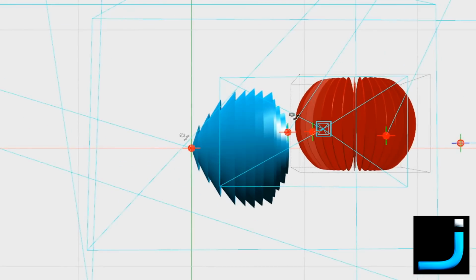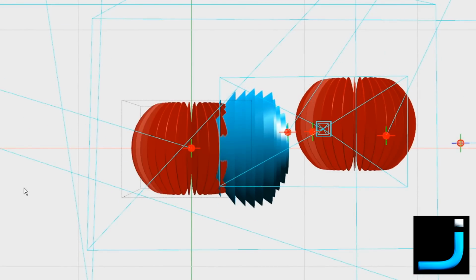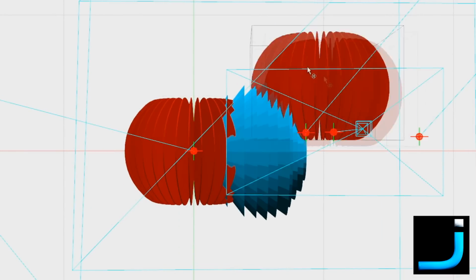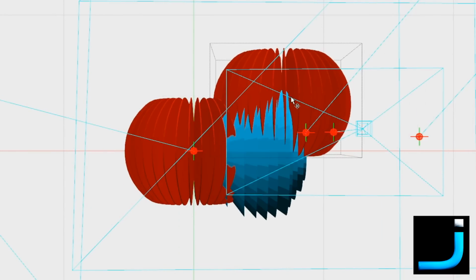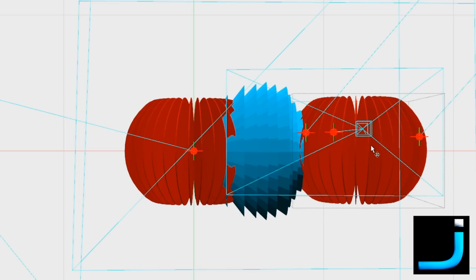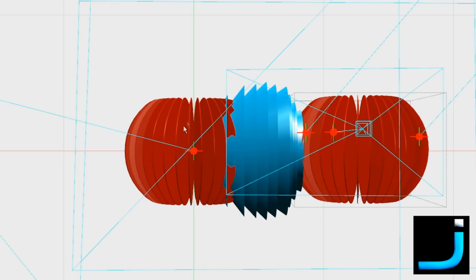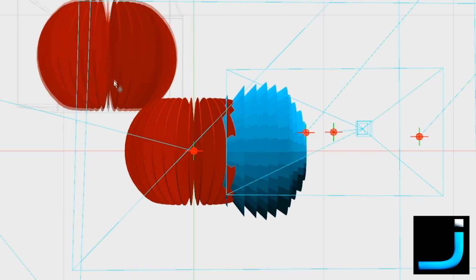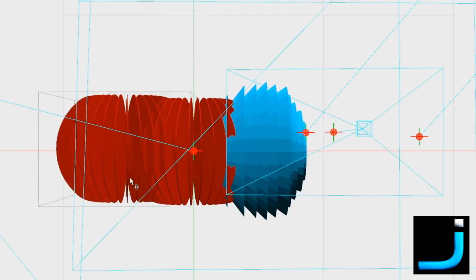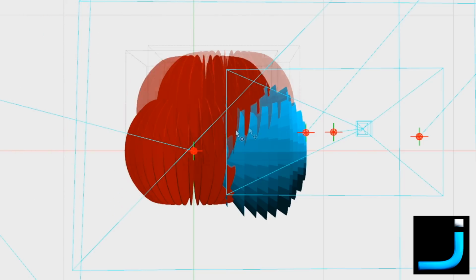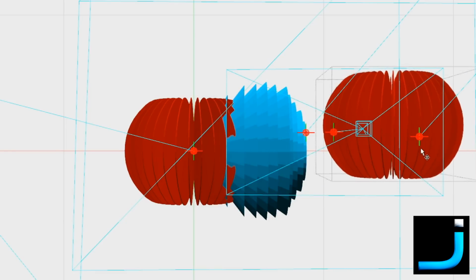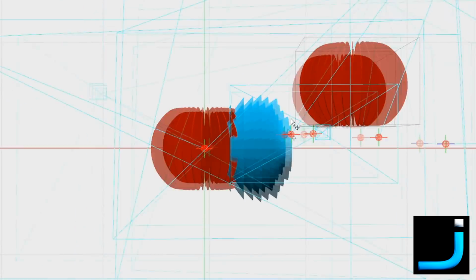So, if we compare the range, which is always an important factor, this is your rubber ducky, and again we would only get to about here, but with the circularly polarized we're going to get a little bit further out because we're 8 decibel versus 2. But obviously the same problem exists. With the rubber ducky we can fly behind and we're all good, or we can fly in front, but with the circularly polarized, only in the field of view.